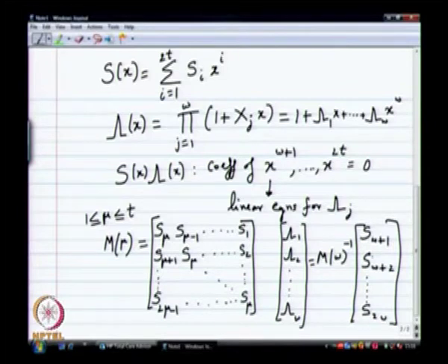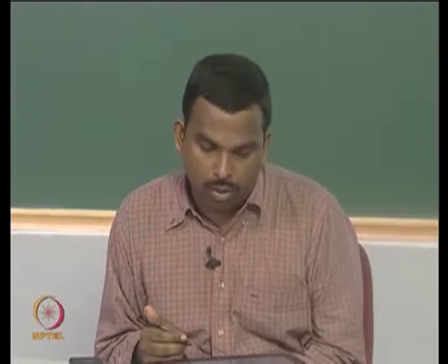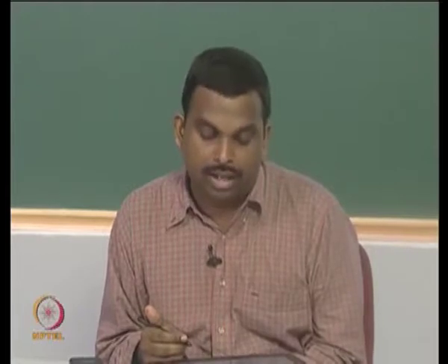You have only found the error locator polynomial. From the error locator polynomial, you have to find the error locators. So, basically you go through your Galois field and find all the roots of lambda of x. If you get exactly w distinct roots, then you have succeeded in your decoding. If anything else happens, something has gone wrong. So, you find the x.